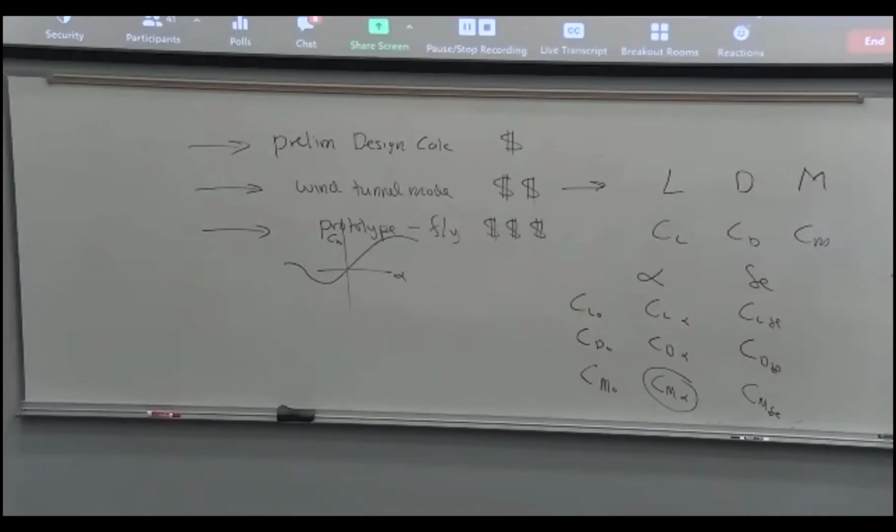And then you do that with the rudder set at different values and the aileron. And so then you can get the model that goes into the math model for side force. And the same thing for rolling moment.